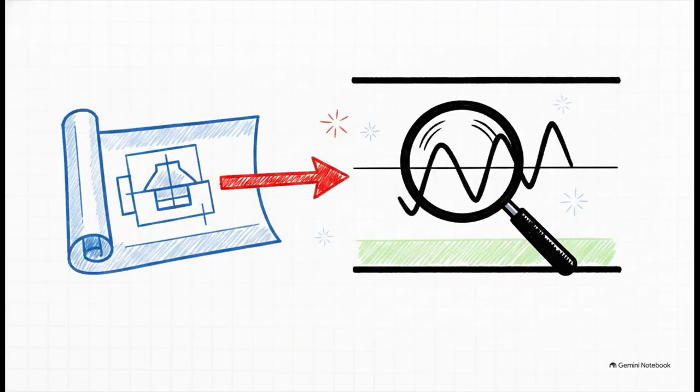But just remember the standard's direct caution. If you do use the statistical tolerancing symbol, the ST modifier, to widen those limits on the drawing, you must clearly specify the necessary statistical indices. The drawing has to mandate that the features be produced with statistical process controls, so the shop knows they actually have to monitor their CPK to maintain that wider tolerance safely.